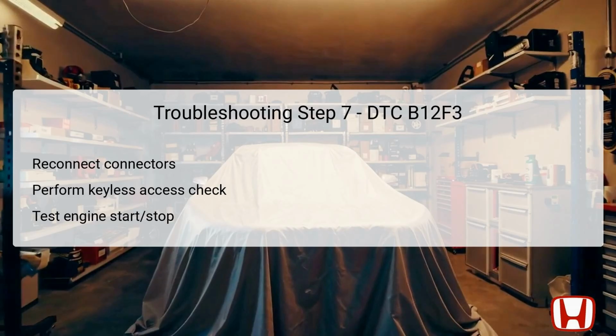The next critical step is to test the keyless access system. Hold all keyless remotes outside the open driver's window while pressing the Start-Stop button. Ensure all doors are closed during this test.